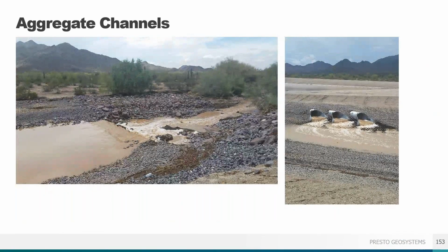Here's the installation under typical flow conditions. You see the technique tip of adding drop structures, and several were designed throughout the channel to reduce velocity before reaching the end of the channel, so water will be transported to the groundwater system. With the aggregate protection system, there's little to no maintenance required. Since the aggregate is confined, it won't need to be replaced, and the channel is large enough to accommodate large storms without overtopping.